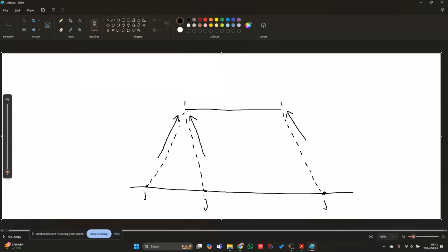In general, we rather want you to just formulate how you're going to get the revolute joint reaction force based on the Lagrange multipliers, what function you're going to use. But in general, I think this is a good convention to use when you're working with something like a Gough-Stewart platform. You want to evaluate what the forces over here are going to be on the platform body. So in that case, I want to use point I on the platform body points, and then point J will be on the grounded revolute points that I have.